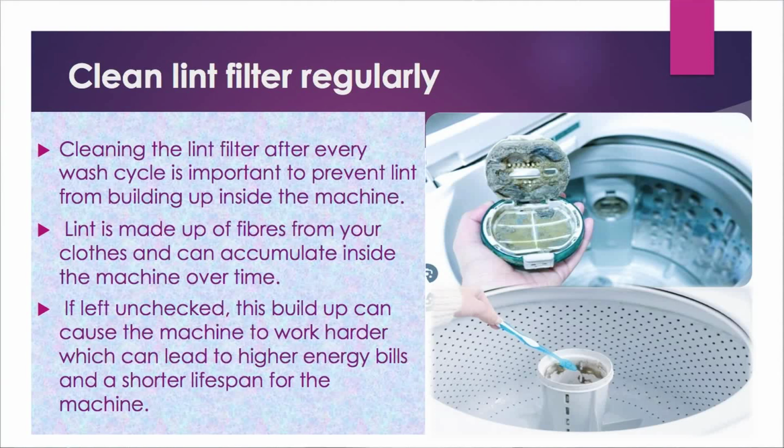Now another important point is to check regularly the lint filter, because it has to be clean. Cleaning the lint filter after every wash cycle is important to prevent lint from building up inside the machine. Generally, lint is made up of fibers from your clothes and can accumulate inside the machine over time. So, if left unchecked, this build up can cause the machine to work harder than it needs to, which can lead to higher energy bills and a shorter lifespan for the machine. Cleaning the lint filter regularly can help prevent this build-up and keep your machine running smoothly.